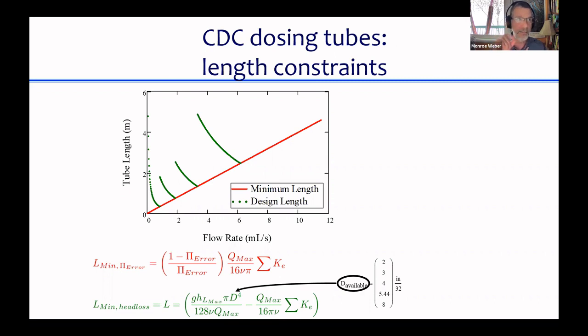So if we increase the height of that, that's more head loss through the plant, a bigger elevation change across the plant. And that essentially means that the building that the plant is in needs to be taller, because all of the difference in elevation and water in the plant has to be accommodated inside the building. And so if you increase the difference in water between the low end of the plant and the high end of the plant, the building needs to get taller to accommodate that extra height.